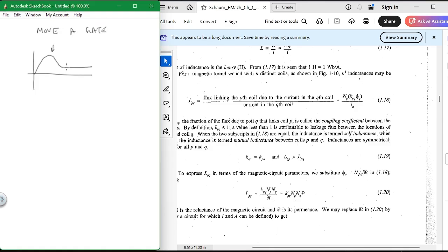With a solenoid that is used in industry, this is about 3 times this number right here. So if this was, let's say, 0.2 amps, this would be about 0.6 amps. This height is about 3 times that height, roughly. Does that matter? It can. When something is open, there's a high current draw. When it closes, there's a low current draw. So you see that difference.